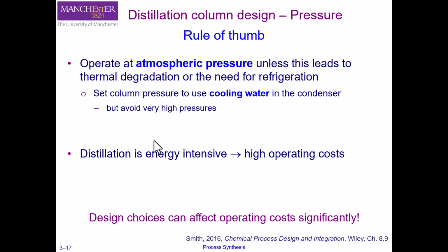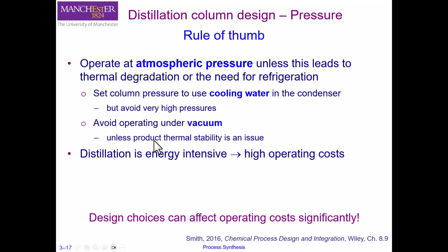The other point is that we should avoid operating under vacuum. A good reason to operate at sub-atmospheric pressure is only to avoid heat-sensitive component damage. By using vacuum, we can operate at lower temperatures without decomposing or damaging the components that are being separated.